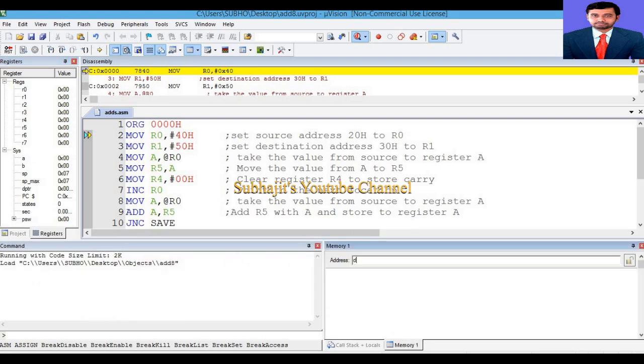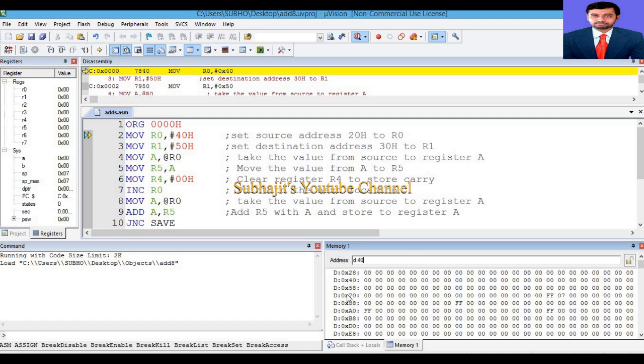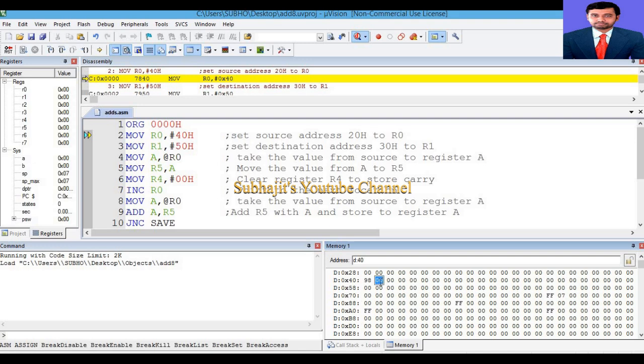And give the RAM address 40. So you can see here the RAM address 40, and I am giving the input to the 40 and 41 hex. So I am giving here 98 and here 99. Then I am running the program with the help of this button.